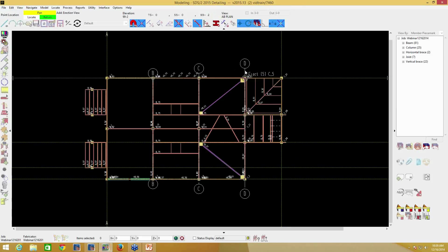The one thing I will point out here is that the extents for what you can view here, when you picked your 2 points with a triangle like before, is going to be the same no matter what your grid bubble setback is. Because I picked the same points for B, C, and D when I was putting in my grid line there, it will see the same extents no matter that my grid bubble setback is different. That has no effect on the extents that you will see in your views there.